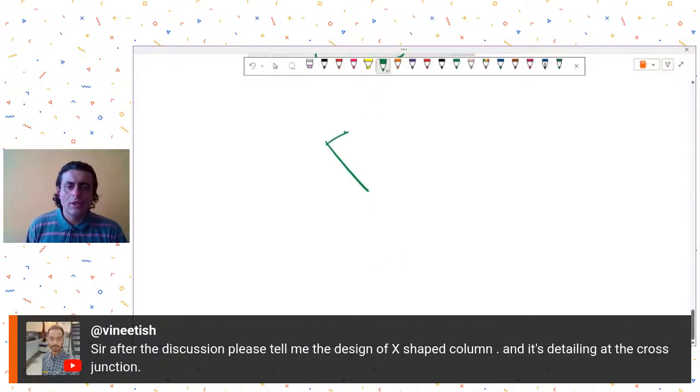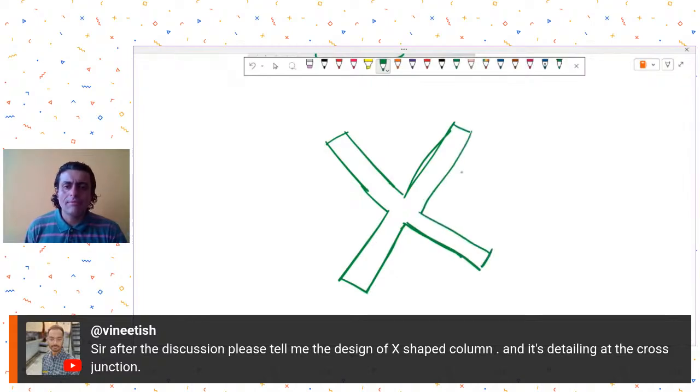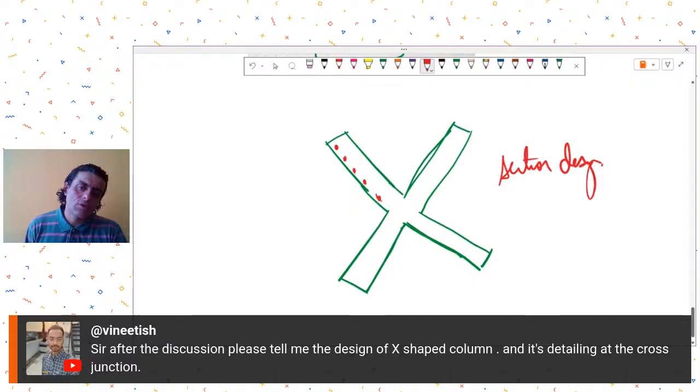So manually you won't be able to calculate the PM diagram. In such a case, you can go to your software like ETABS, create this section in section designer, put the reinforcements, and decide how you are going to place the reinforcement arrangement depending on this thickness. I guess you can continue doing like this.